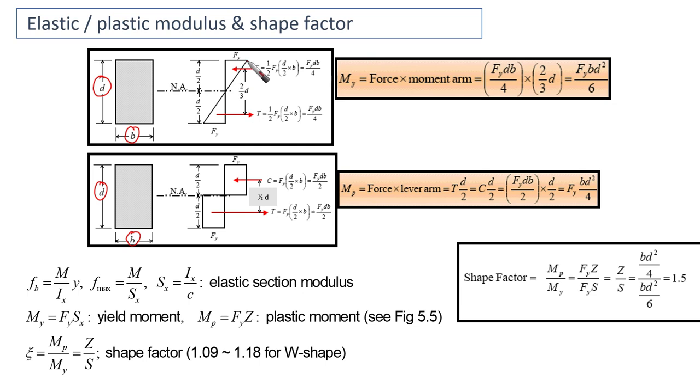Starting from the beginning, you're going to find, first of all, the neutral axis, as we said, whether for elastic or plastic modulus or elastic or plastic sections, it is going to be in the middle. Here, because we have a triangle, the centroid of the upper half for the forces, we call it C. This C is going to be the area of this triangle multiplied by the width, right?